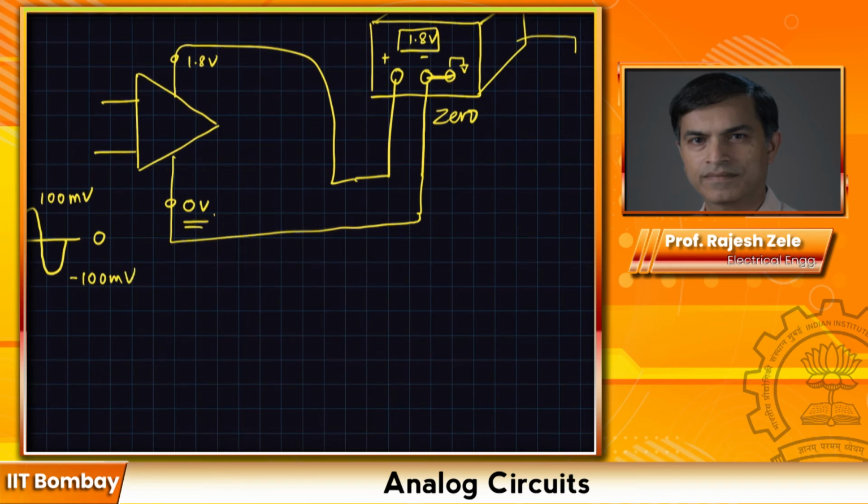That's the reason we use something called analog ground. Analog ground is something like a reference in our head that we use all the time. In this particular case, we could say, let's define VDD divided by 2, which would be 0.9 volts, and that would be our analog ground.